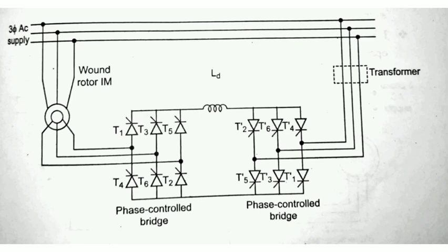Rotor voltages at the slip frequency are used to commutate the thyristors present in the converters. At low speeds, the voltage across the rotor will be less and it may not be sufficient to naturally commutate the thyristors. This difficulty can be overcome by using forced commutation. It means that additional forced commutation circuitry is necessary for the Scherbius drive, where both below and above synchronous speed operation are possible. Also, the Scherbius scheme requires 6 thyristors in place of the 6 diodes present in a Kramer drive. Hence, the drive becomes costly compared to the static Kramer drive.